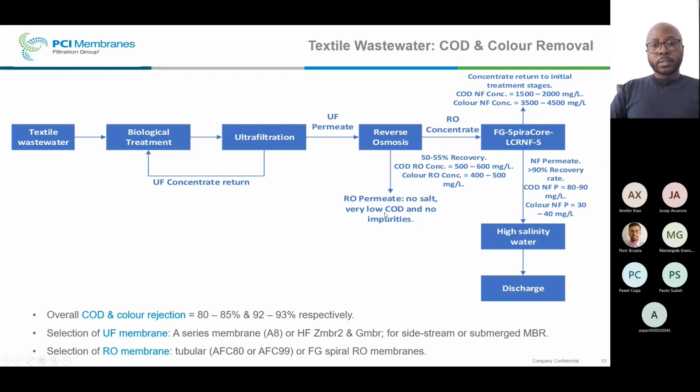The COD content is minimal. Of course, it depends on what's causing the COD in the production phase. If this is of alcohol origin, it is likely that some COD will pass, but in this case, the COD is mainly due to the organic constituent of the dye. So we have a very high retention of the COD, and therefore a low passage of the COD into the permeate stream. For this particular case, the recovery rate of the reverse osmosis was in the region of 55% recovery. So a significant recovery of the water stream.